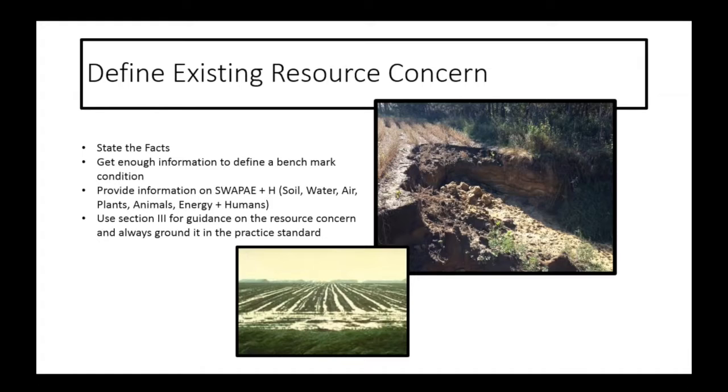So when we see a concern, and this is obviously two examples of a concern, we have one on the right-hand side where we have probably some lateral flow, in the top photos, in some soils that have some pretty poor structure. So it's starting to collapse and cause failure. So we're losing it. Could be spring frost causing it. Probably isn't a lot of surface water, although we tend to think that when we see big erosion problems like this, but something's causing a major failure. So we've got problems with lateral flow now.